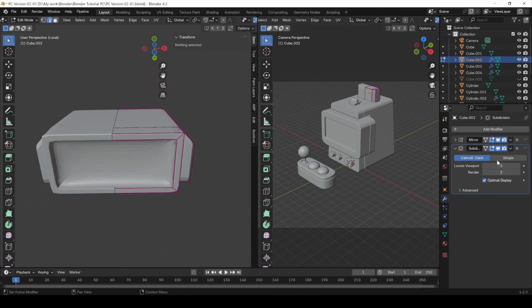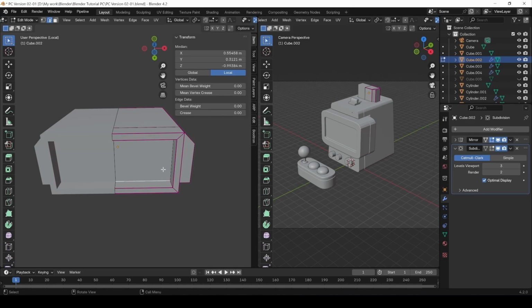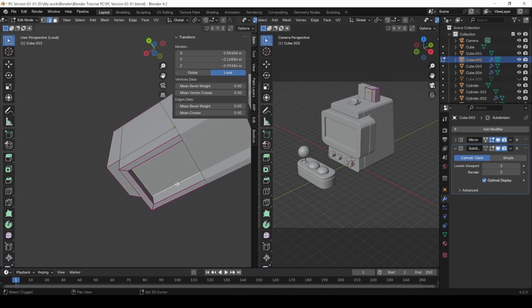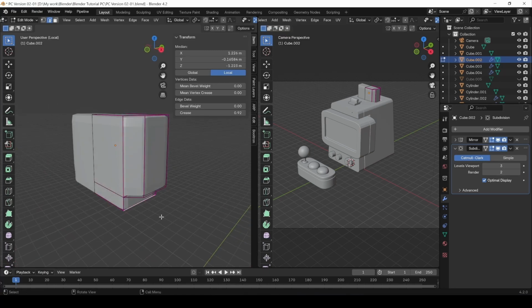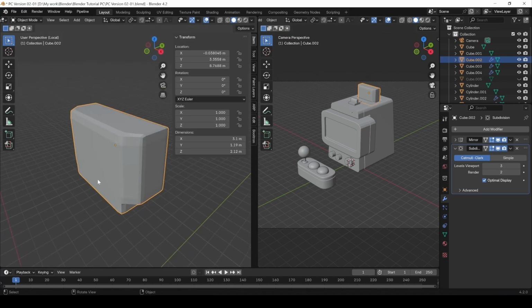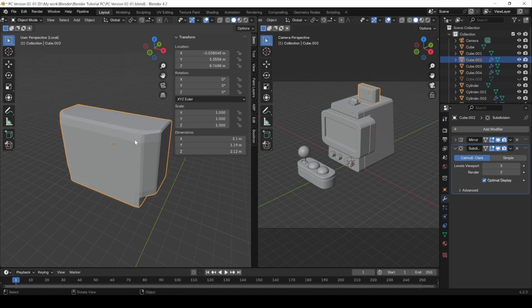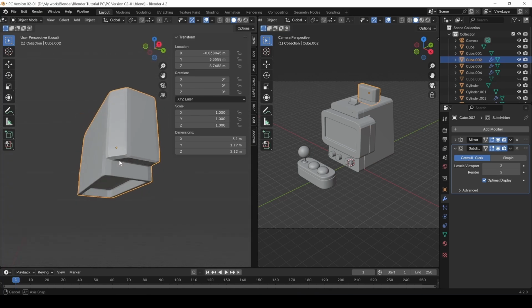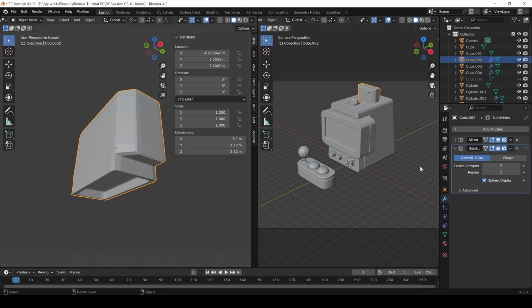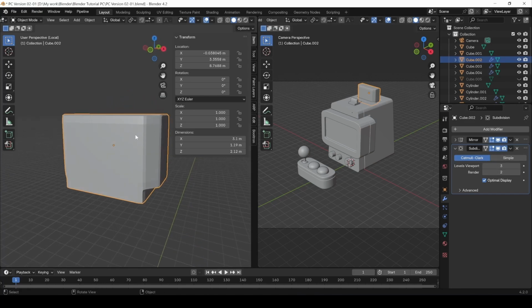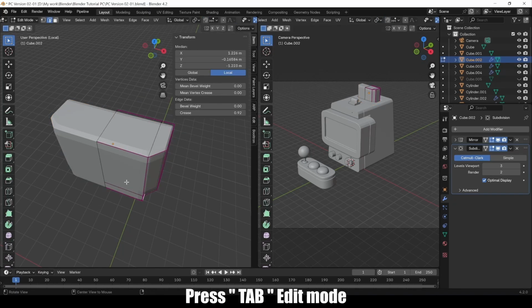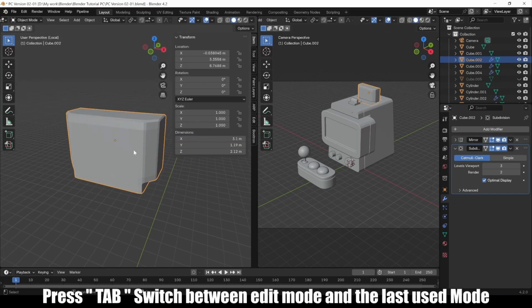Let's choose this again and do this, because I want to smooth this inside too. So go to it and just increase with Shift E if you want to. Okay, now let's get it like that. Now it looks like this, which makes it pretty nice. As you can see now it seems that you have a bevel tool without really using the bevel tool, and in a very non-destructive way. At any moment you can just go here and modify this to get a different bevel. You can modify the edges and you get a different bevel without being destructive.